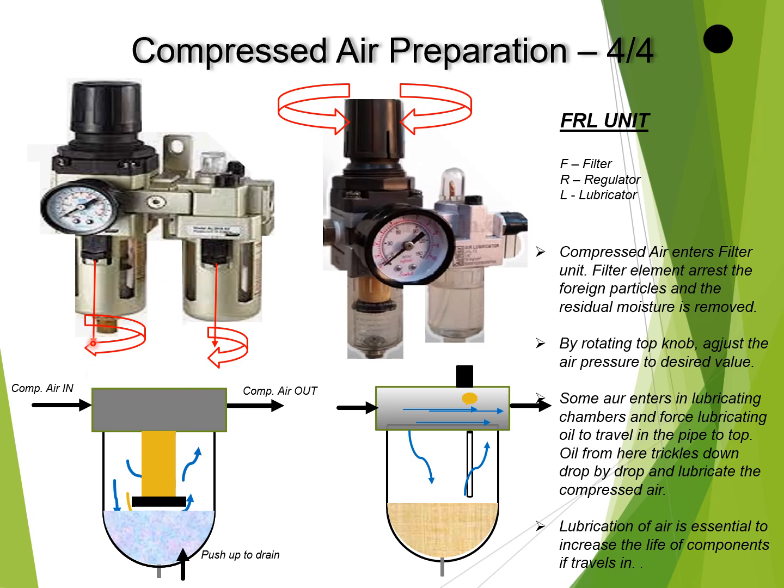The cleaning of the filter unit can easily be done. You can pull down this switch, rotate it, and this metallic portion can be removed. Then you have a glass portion. By removing this glass portion, if you want to clean the filter, you can clean it. If you want to change the filter, you can change it. Similarly, if you want to top up the lubricating oil, you can remove it and top up the oil.